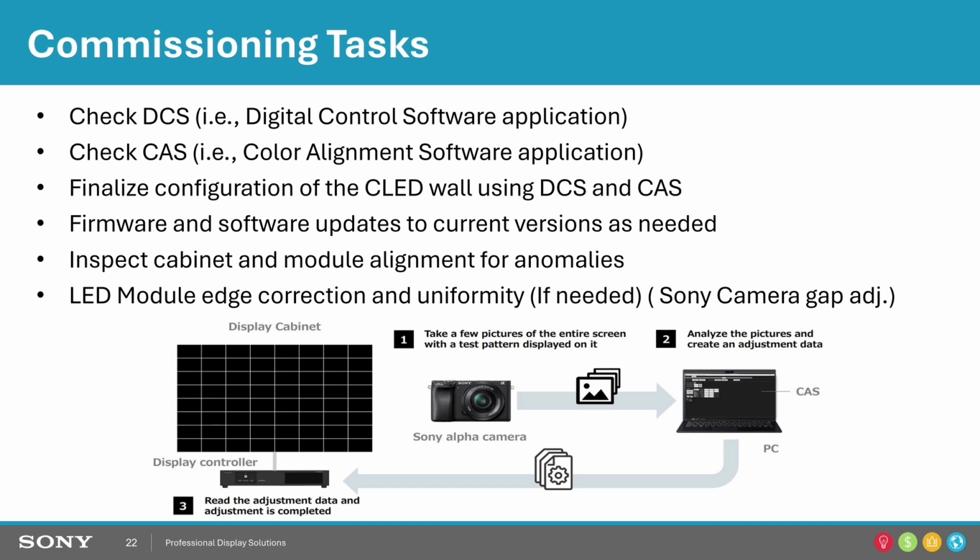And to Chris's point with the laptop, the maintenance laptop is really required. It's also a great time-saving tool, because if you send one tech on site and that tech doesn't have the right software level, or the correct DCS software, or doesn't have it at all, it causes confusion and sending multiple techs. The laptop is always there. There's no time wasted trying to find the right software, the right DCS firmware, all these things. So it's a great tool, and it's really encouraged to have one on site.